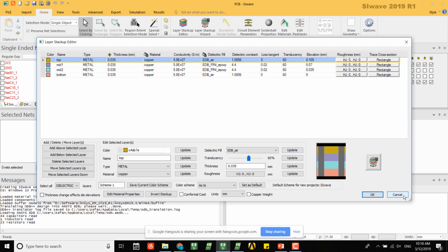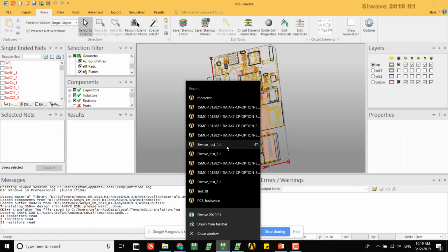So when you export the design, usually you need to look carefully at what you are exporting, and when you import it, always double check. Because this file is open source, I'm not sure whether the problem comes from the other side or my side, but I will import the dielectric layers manually. So here I have a design which already has the dielectric layers.